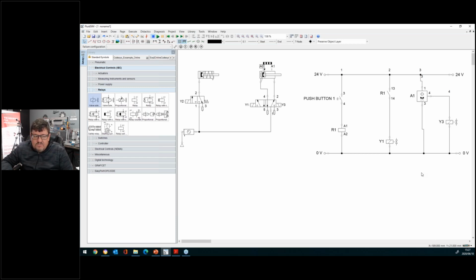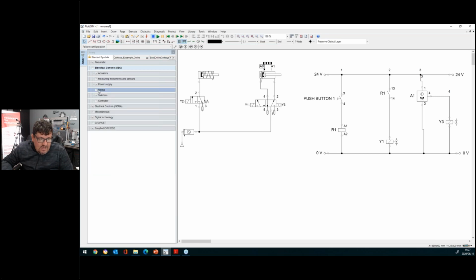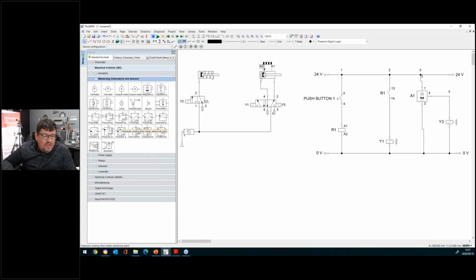Okay, sure guys, to answer that question, what is a pressure switch? A pressure switch, remember now, is actually an electrical contact. When you set the pressure switch, for example, let me assume 5 bar, your pressure is rising from 0 to 5 bar. The moment it reaches 5 bar, a contact closes, and that signal will be utilized in your control circuit.